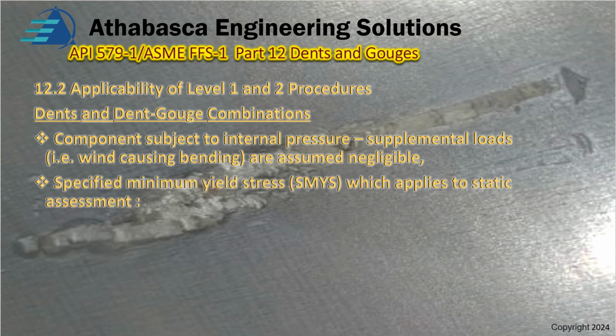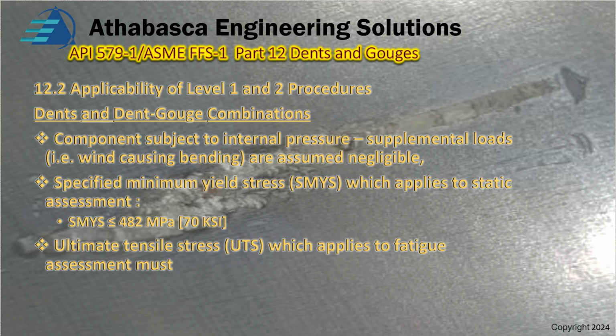There are also conditions on the material properties. The minimum yield stress, SMYS, applies to the static assessment if it's less than 70 KSI or 482 MPa. Also, the ultimate tensile stress, the UTS, applied to a fatigue assessment must be less than 710 megapascals or 103 KSI.